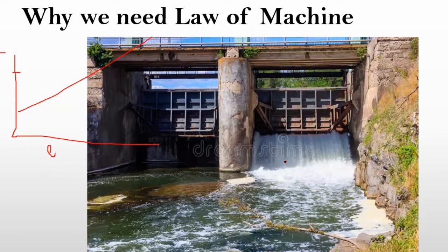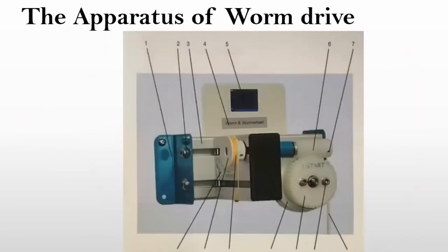Based on your requirement of water, you calculate the gate opening at this load. So you can calculate from the law of the machine how much effort you need to give, that means how much the motor will rotate. So that's why, whatever mechanism we look at, we are interested in the law of the machine.